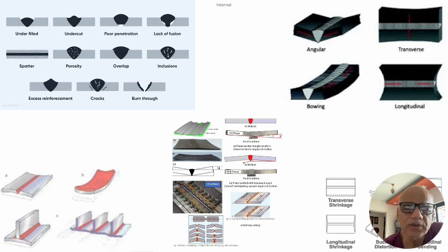Porosity most of the time is internal, very rarely, or sometimes, you can see it on the surface also, open to the naked eye, and you can correct it. But surely an experienced welder can see the gas which is bubbling into the weld pool, and if it is having a very aggressive action there, then porosity is surely going to come.